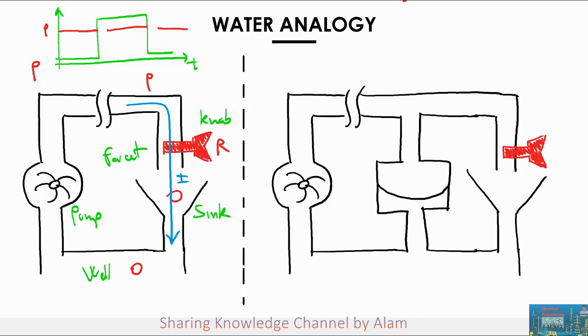If this is really a hydraulic system with a very long plumbing, the moment you open the knob, a large amount of water will be allowed to exit the faucet. Remember that the pressure is a representation of the presence of a large amount of water in a tight space. The moment you allow the water to exit your faucet, all of a sudden your pressure has to decrease because there's just less water available to generate that pressure. As a consequence, the moment in which you open your knob, the pressure will suddenly drop, and later it will recover thanks to the action of the pump.